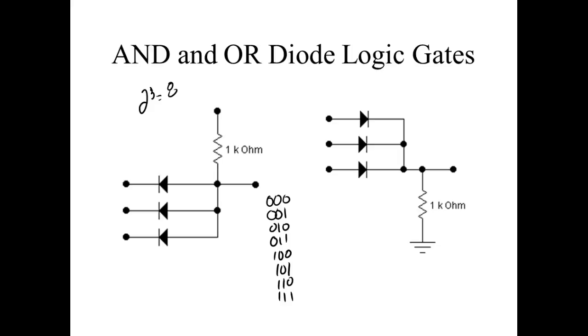By the way, we call these gates because you can see how it got the name: if I've got all ones over here, it lets the cows go through. So basically, it's opening up the gate. If any of these inputs go low, then the gate would be closed, and that's how it got the name, right? You understand? So we say only one combination would open the gate, would let the high inputs get through and make a high output, right?